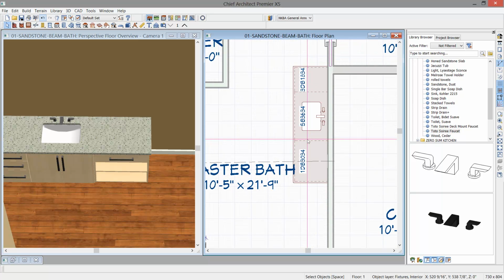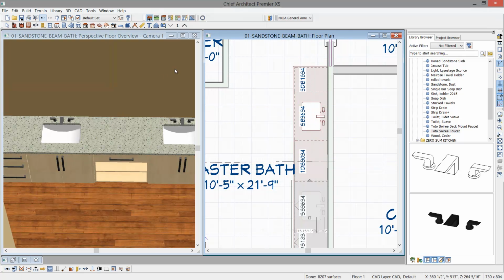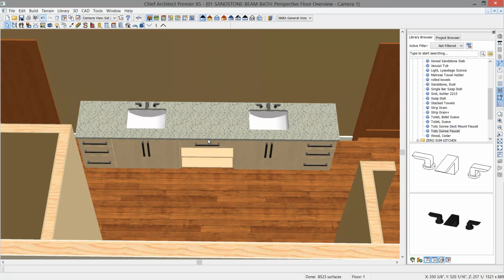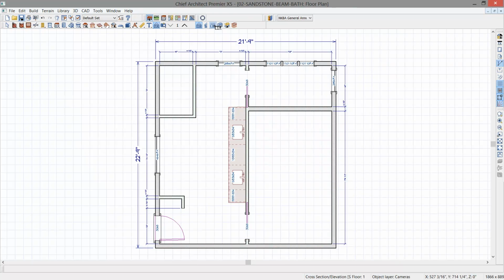Now, to grab and replicate these two cabinets, I'm going to highlight the sink, the cabinet with the sink, and the cabinet to the left of the sink. Use my copy, reflect about the center, and rotate that around. So there is my vanity run completed. Now the next step is we'll look at changing the colors, do our elevation, and also adding our backsplash behind the cabinet. I'm going to use the wall elevation camera and take a wall elevation of the cabinet wall that